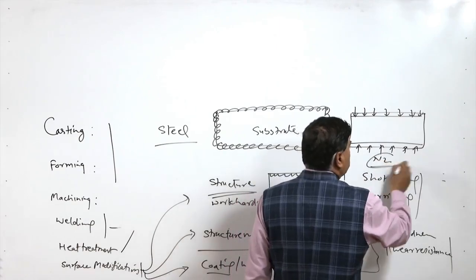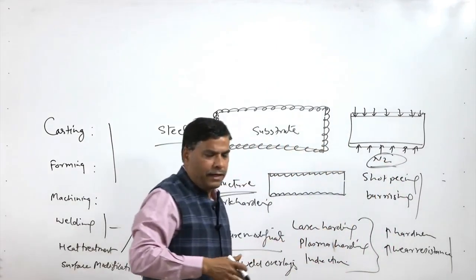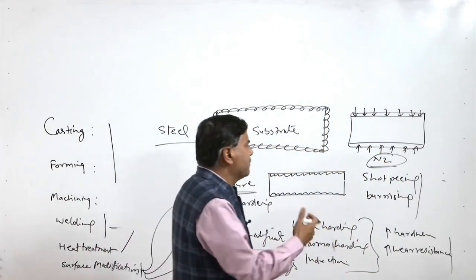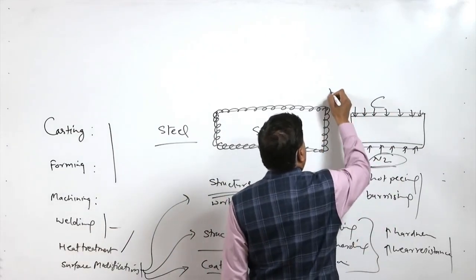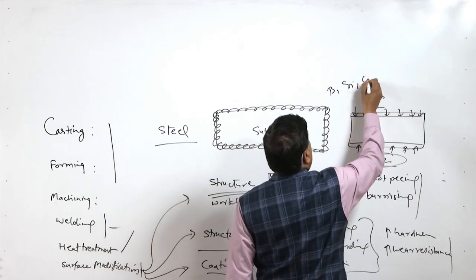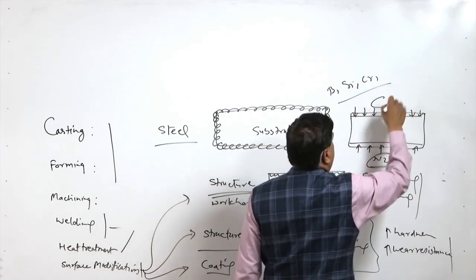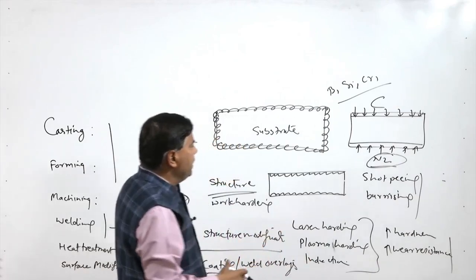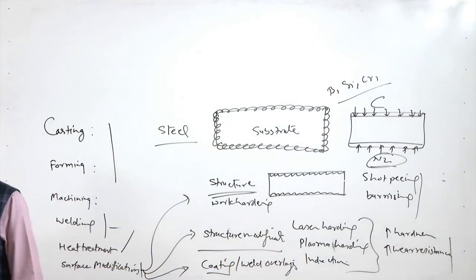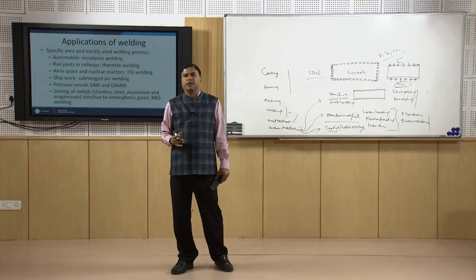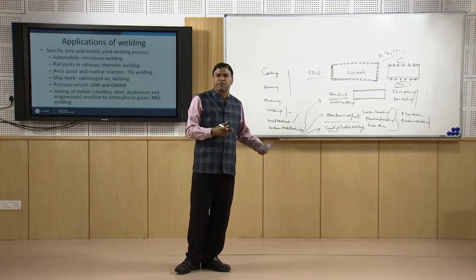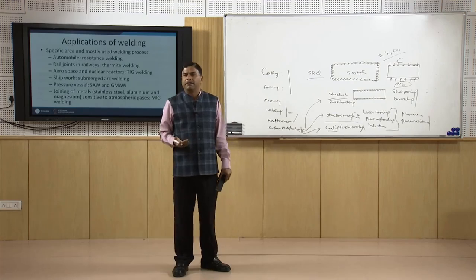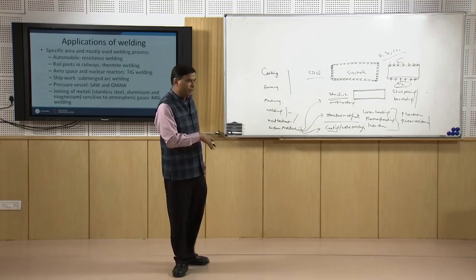As per the application, different elements are introduced like carbon, nitrogen, boron, silicon, chromium. All these are introduced suitably, so that the surface layer is enriched in order to achieve the desired combination of properties, which is primarily improving the hardness and wear resistance in case of surface modification.